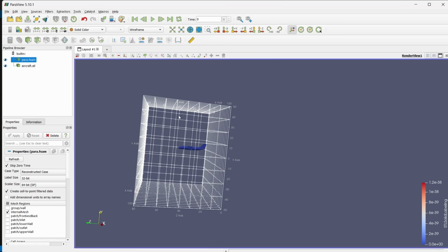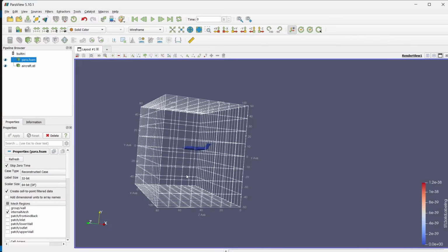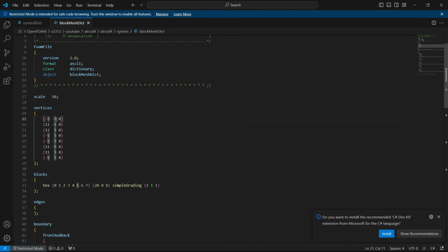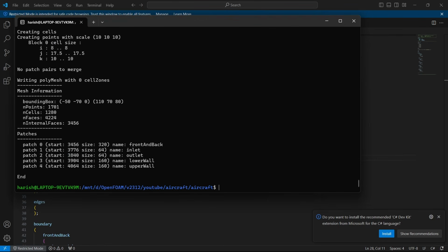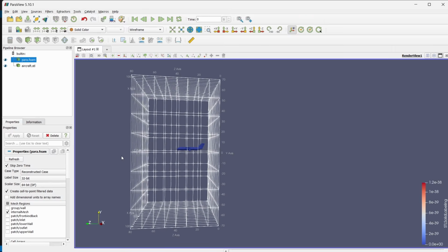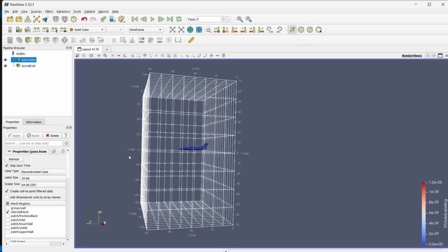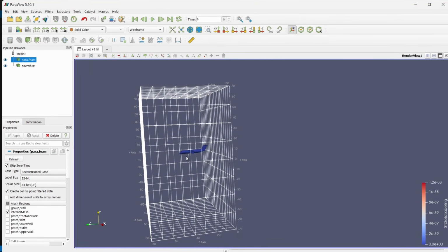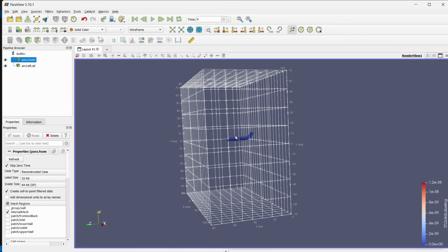As you can see, the Y is now decently big, but I think it is not yet sufficient. So I will probably go up to 7. But if you have a specific dimension to work with, then please go with that, because whatever I'm doing in this tutorial is not to run the case, but instead just to demonstrate how to work with snappyHexMesh. So you just follow the proper physics and maintain the distance between walls and the geometry properly.